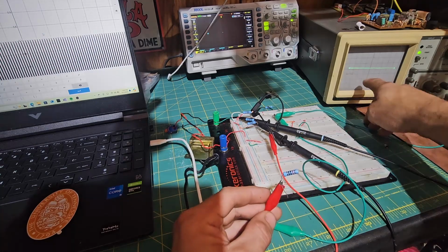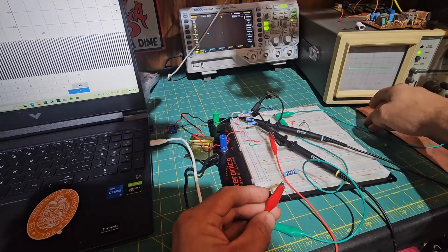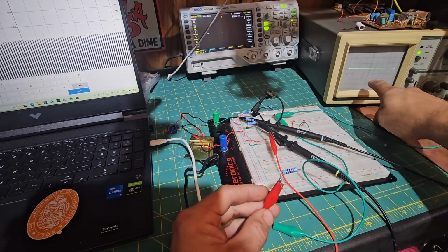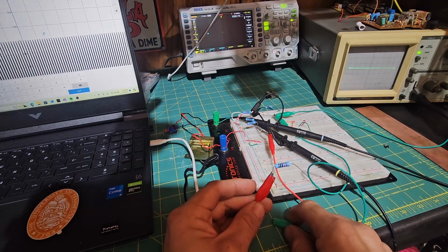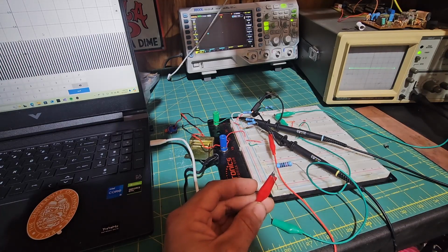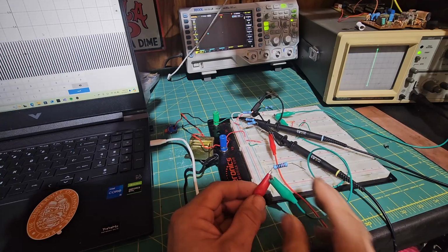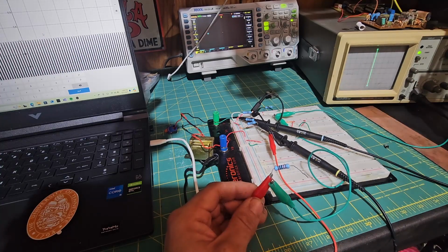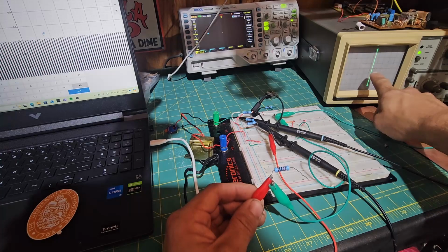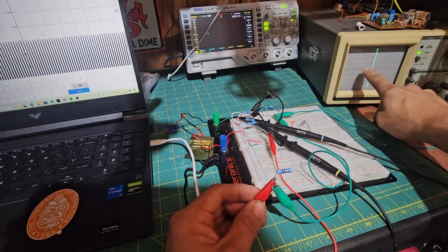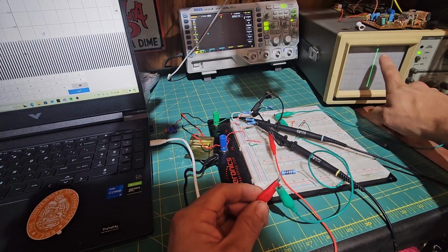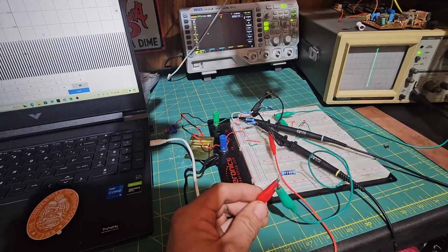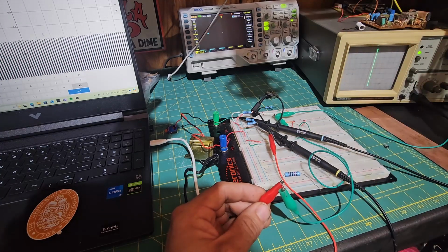Now the y-axis on the scope is drawing a current. You can see I have an open probe, so there is no current flow because there's no path between these two test leads. But if I were to short them out right here, the line goes completely vertical. The reason why is that since we have a dead short, the voltage is no longer allowed to rise horizontally anymore. It can only rise vertically up and down, because the circuit at this point is all current and no voltage. So close to zero impedance.